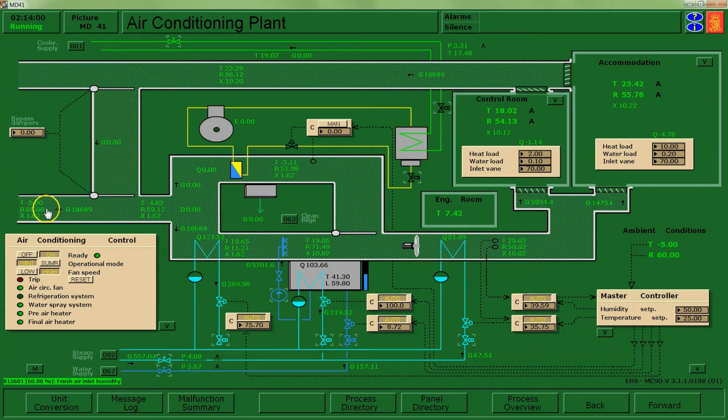Okay, so let's look through what happens now. We bring in cold air from outside. It goes through a heater section. It then goes through a humidification section. And then we have a final heating to get to our comfort conditions. Once again, depending on heat load, we may not hit our targets in some of these areas. Heat losses and heat gains may not mean that we get the right temperature in either space. So once again, you may need to adjust your dampers, adjust your set points so that ultimately you can get to comfortable conditions inside of your spaces.